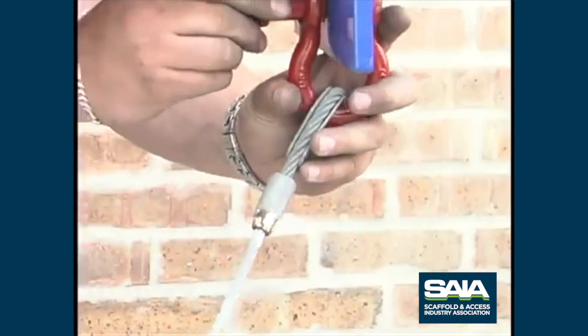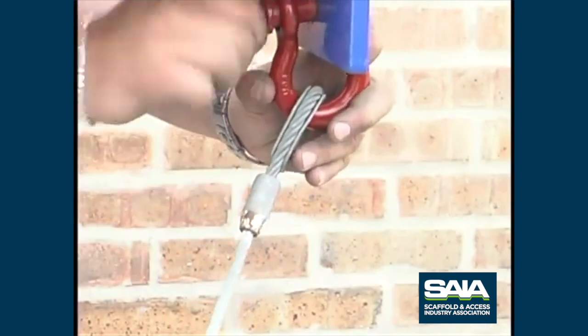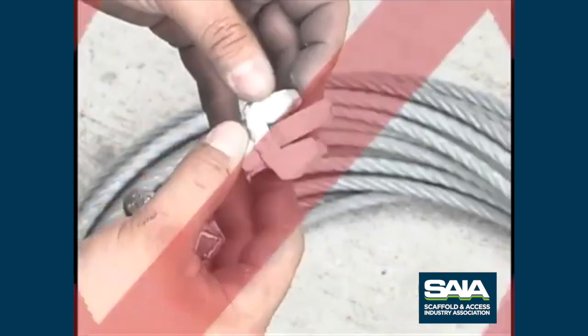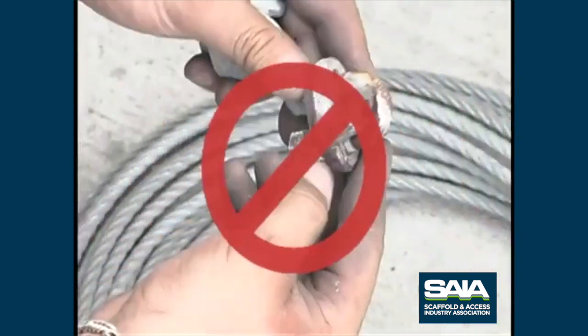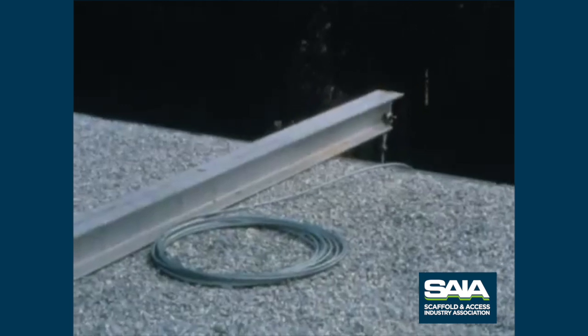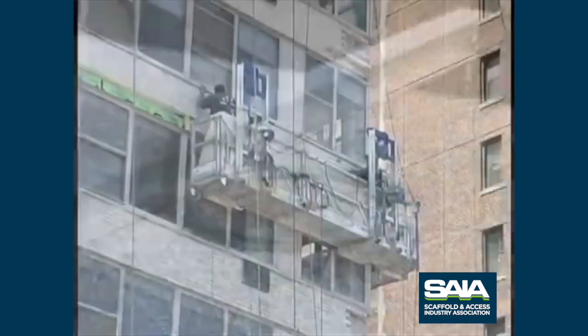If a swage fitting is to be used, the swaging must be done by a qualified person or the rope manufacturer qualified in this area. Do not use U-clamps. Excess wire rope can be easily damaged. Store excess wire rope at the roof or suspension level to minimize damage.